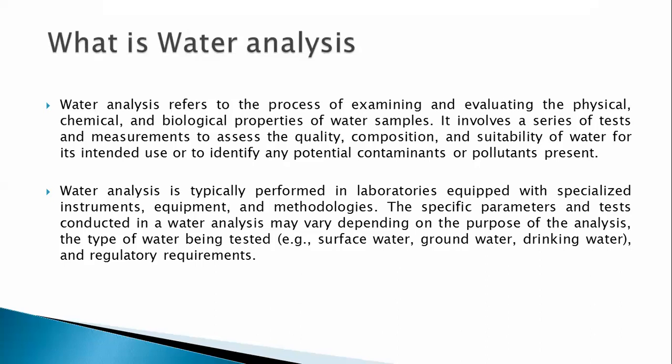But for the microbial lab, they will tell you to pick your water sample being mindful of the fact that the vessel you are going to use to pick that water sample is sterile. What you are going to use to cover that vessel is also sterile. Everything is sterile, so that you are actually checking for microorganisms in the water and not microorganisms that have already adhered to the container with which you picked your sample. So picking of sample for microbial analysis will be different from picking of sample for chemical analysis. You can just use any vessel, any glassware, to pick your sample. But for microbial analysis, you would have sterilized your glassware.